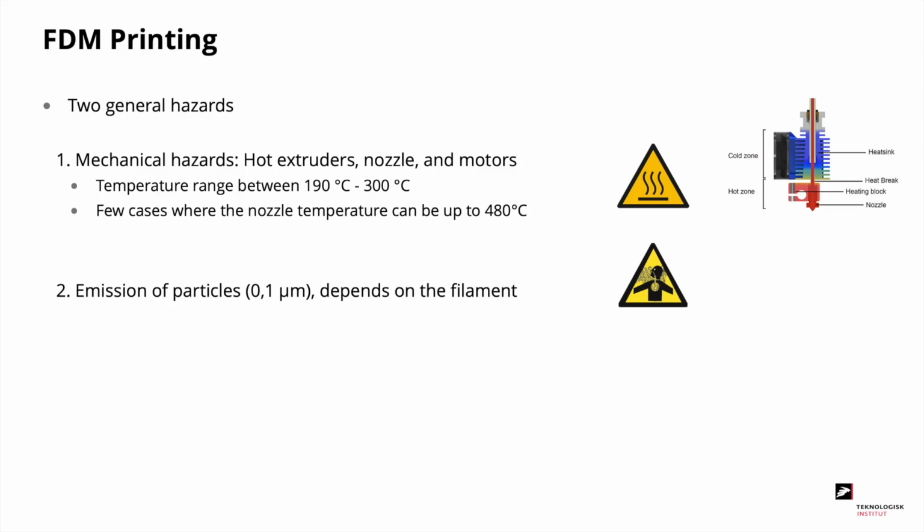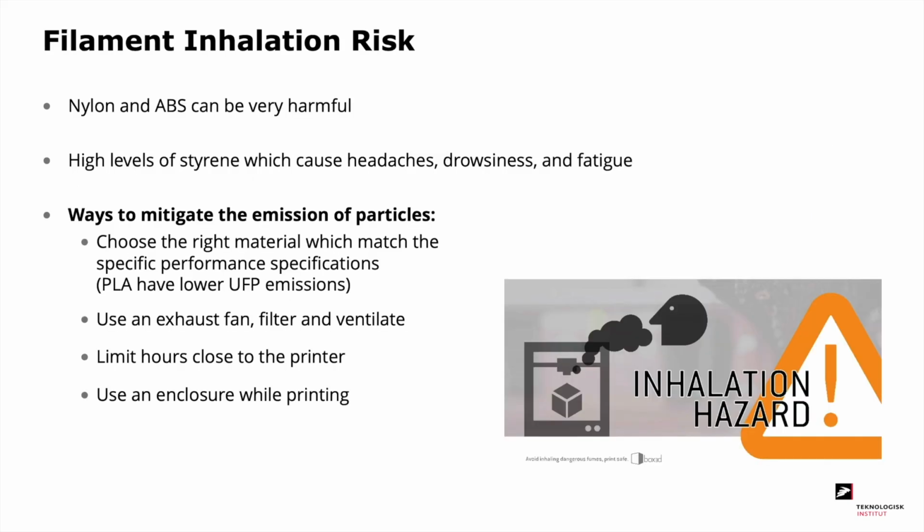The second hazard is the emission of small particles down to 0.1 microns, depending on the filament. So this is an inhalation risk. Looking at the filament inhalation risk, we have nylon and ABS that can be very harmful. The high levels of styrene can cause headaches, drowsiness and fatigue, but there are several ways you can mitigate these emissions of particles.